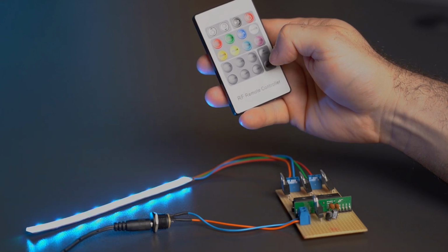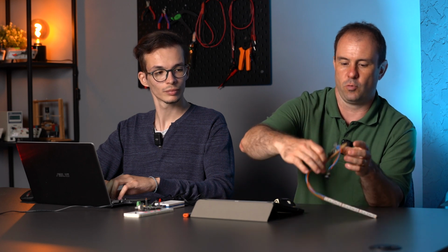which is a small controller built into the panel. Of course, it can be used to control long LED strips, but the output of the microcontroller wouldn't be able to power it, so the LEDs are driven by an N-channel MOSFET. Here you can see the 3 MOSFETs needed to drive the 3 channels and the 3 different colored LEDs.